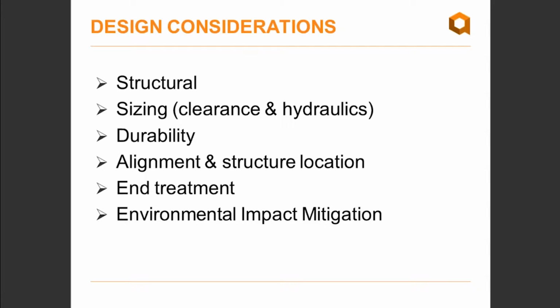You'll need to properly size the structure to basically address any roadway clearance requirements in an underpass or grade separation. And in water crossings, you need to address any hydraulic conveyance requirements or end area. Durability, as everyone knows, is a big one, and as these structures need to last for the intended service life, they do need to be designed appropriately with a consideration to the specific environmental parameters of the site you're looking at. So we'll be covering how to do that today.